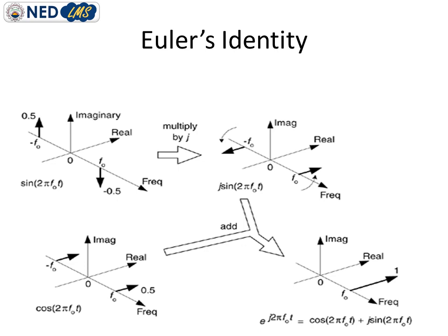It means that sine wave and cosine waves are added up together to formulate a complex exponential signal. And at the end of this slide, you came to know that sine wave or cosine wave have double-sided spectrum, but for the complex exponential signal, we have only a single-sided spectrum, and its magnitude is same as that of the original signal.